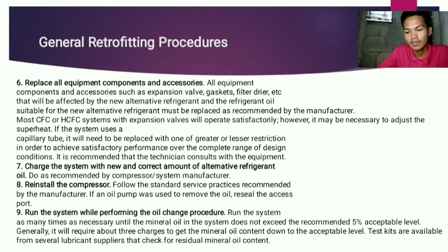Most CFC or HCFC systems with expansion valves will operate satisfactorily. However, it may be necessary to adjust the superheat. If the system uses a capillary tube, it will need to be replaced with one of greater or lesser restriction in order to achieve satisfactory performance over the complete range of design conditions. It is recommended that the technician consult with the equipment manufacturer.